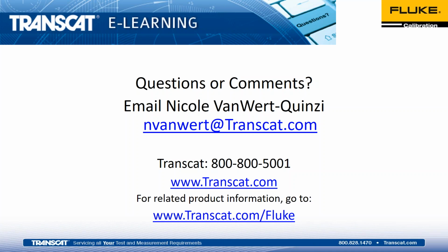All right, next question. Can I use a PLC to control the temperature of my dry block? Yes, most of our dry blocks that we manufacture come with a full serial command set. So if you've got something you're interfacing with, you can interface with them and use remote software. A lot of folks use LabVIEW. We also have our calibration software, and the 1586 has drivers to drive most of our dry wells and baths.